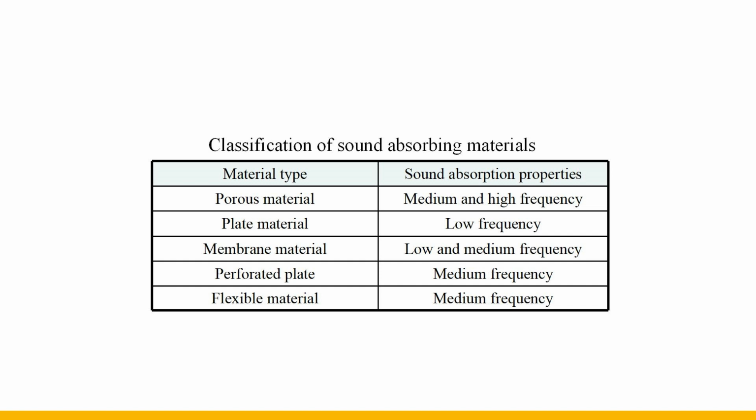Due to the viscous resistance of the air, the friction between the air and the hole, and the heat conduction, part of the sound energy is converted into heat energy and lost. It can be seen from this that only materials with holes open to the outside, interconnected with each other, and deep inside the material have the ability to absorb sound.